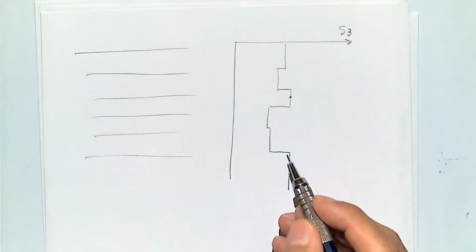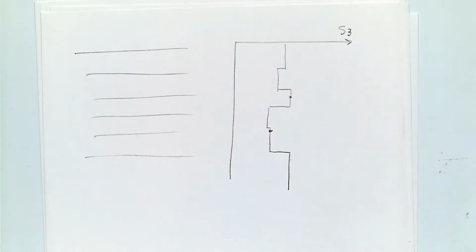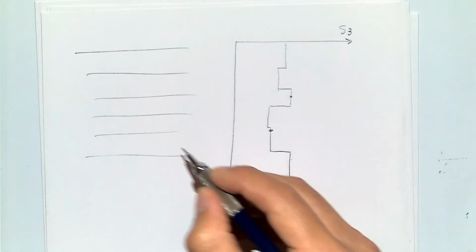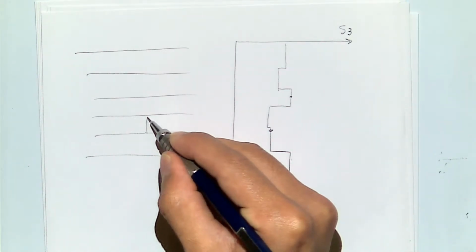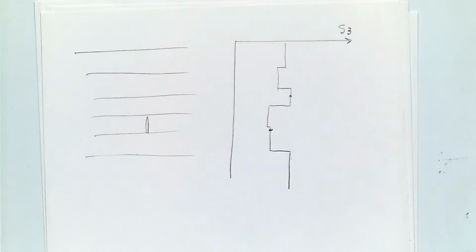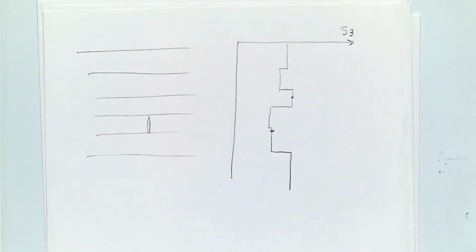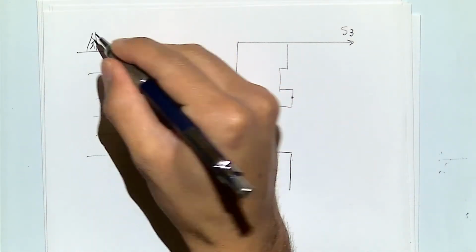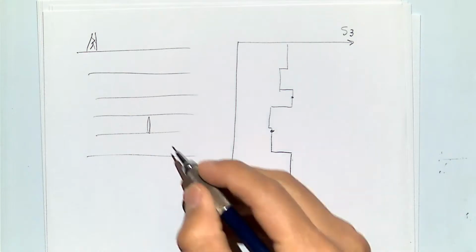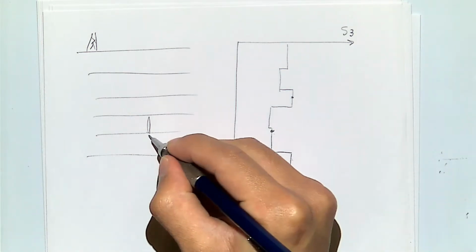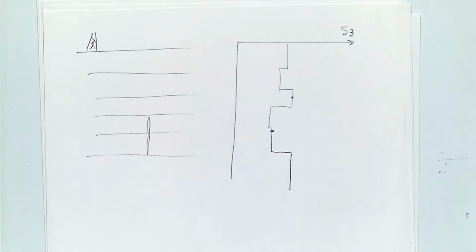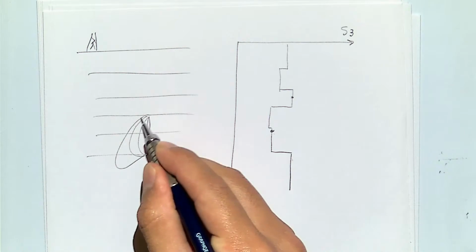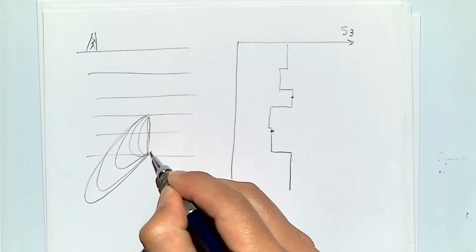If you were to start it somewhere over here, it will tend to propagate, probably first open up in this layer that has a little bit less stress, and then as you continue increasing the pressure in here, it's going to propagate down, and after it will just start growing out of the plane in this direction.